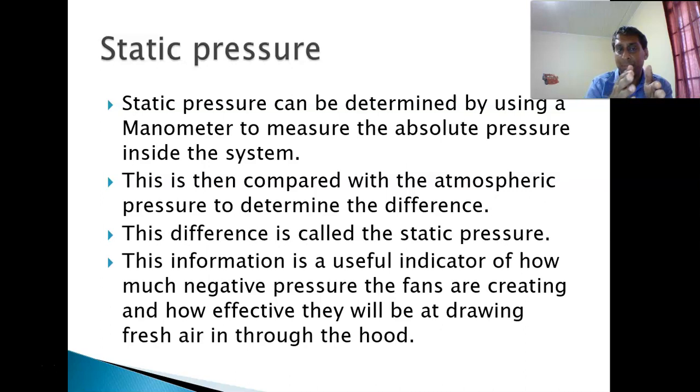This is the fan inside of the LEV system. After the fan, you have to have push, to keep pushing the contaminants out of the LEV system to the atmosphere. So after the fan, you also have static pressure, but it needs to be positive to create that particular push. Let me see what I put on this slide here for you all. So low static pressure can indicate that there is not enough suction in the LEV system to draw the contaminants in.